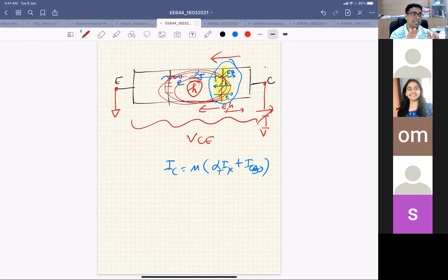The process is that there is a positive feedback coming in, right? And because of that positive feedback, here your M doesn't become very high, your M alpha. So for BVCBO to happen, your multiplication factor M should become infinite. But here it is not necessary. Your M equal to 1 is enough for breakdown, right? And this happens because there is a positive feedback coming into the picture. So breakdown happens very quickly, in the case when the base is open.